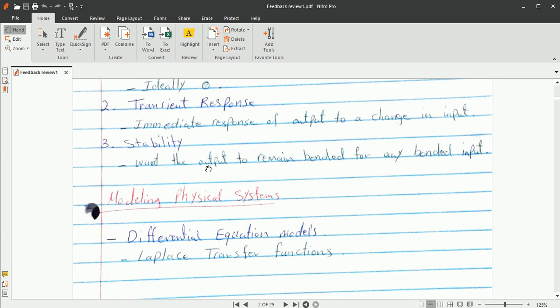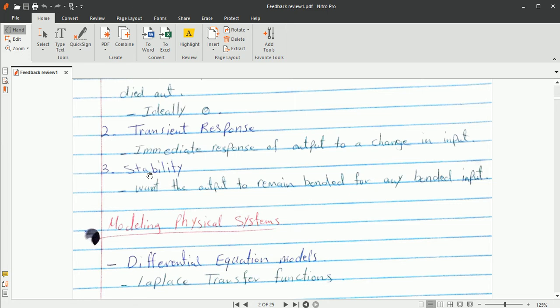There are various criteria like the Routh-Hurwitz criterion, and then we have frequency domain methods like gain margin, phase margin, and Bode plots. So these are the classical techniques by which we determine the stability. There are some advanced techniques which are being used in research, especially I have used the Lyapunov stability theorem. That is another part, but it will not be in this course.